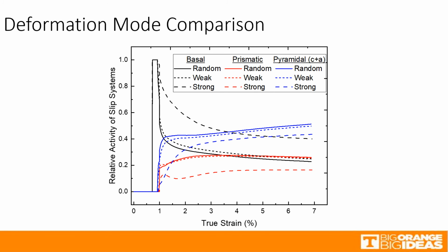This keeps the stress in other directions low and reduces the number of active slip systems until larger plastic strain is reached. This could explain why the yielding region of the strong macro curve is shallower than the weak and random grain set.